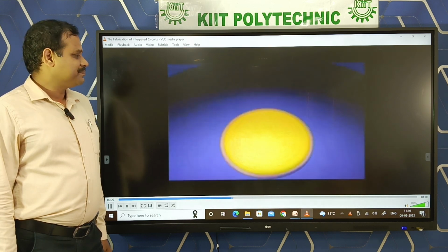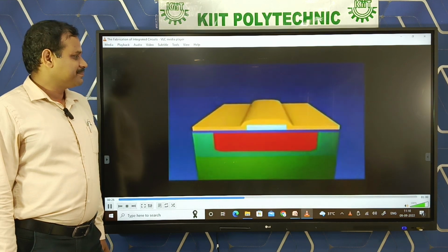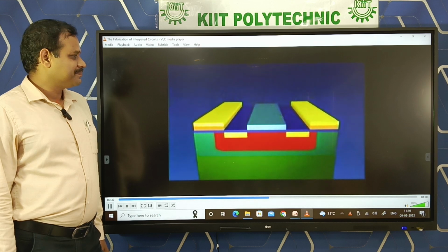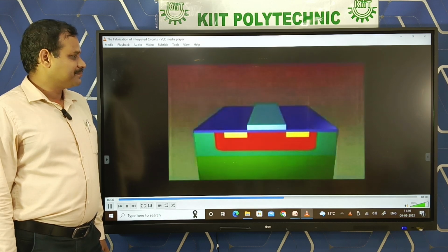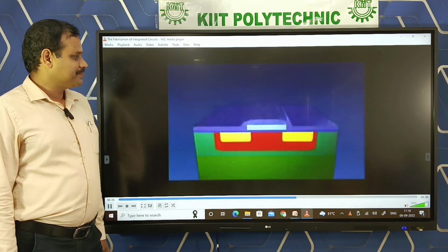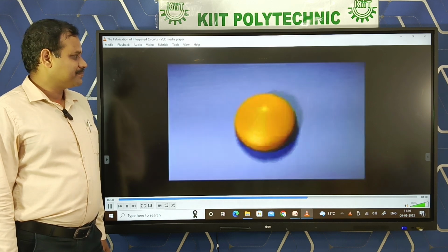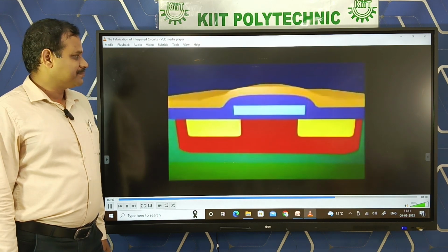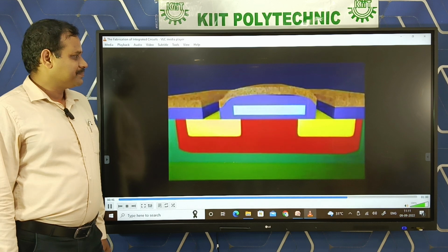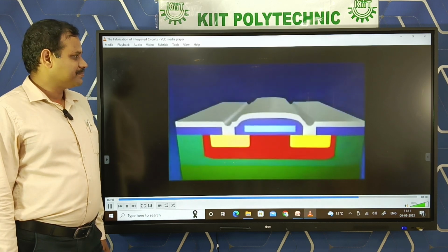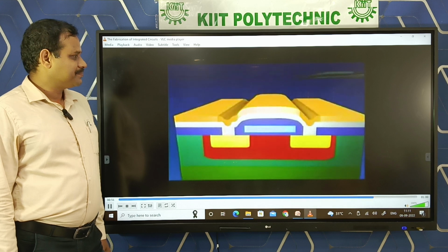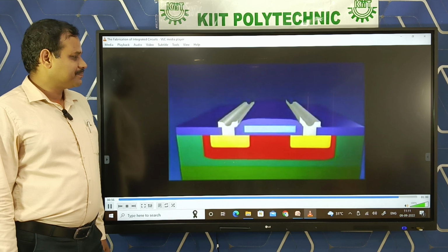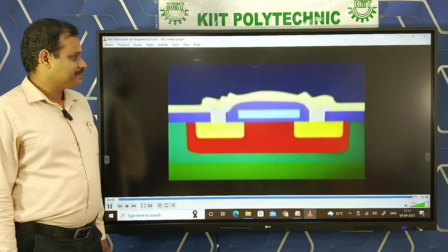Another series of treatments involving lacquering, exposure, bombardment with atoms which penetrate the silicon, new oxide layers, etc. is performed until the whole pattern is complete in all its layers. Some 300 to 400 process steps are required, along with 15 to 20 different masks with microscopically small patterns. The final step in the process is the connection of the various, almost invisible, tiny elements in the silicon.